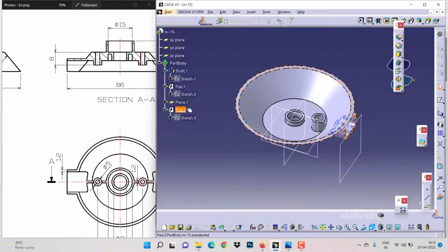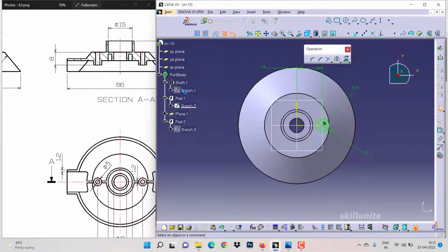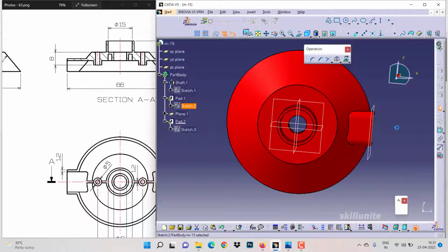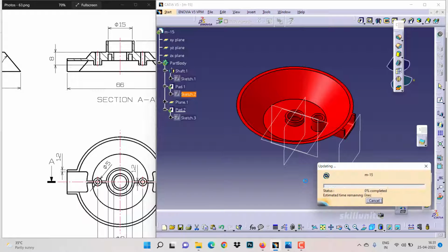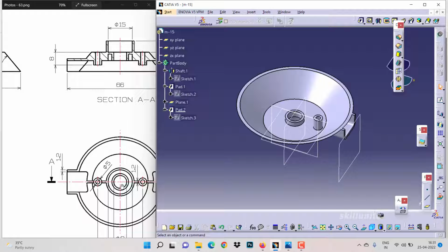So we made a small mistake here. This pad we are having, this is outer itself, it is diameter 5. So create it accordingly. Then make an update now. So now this is the right value. So now we can remove the cutout, we can remove the material.